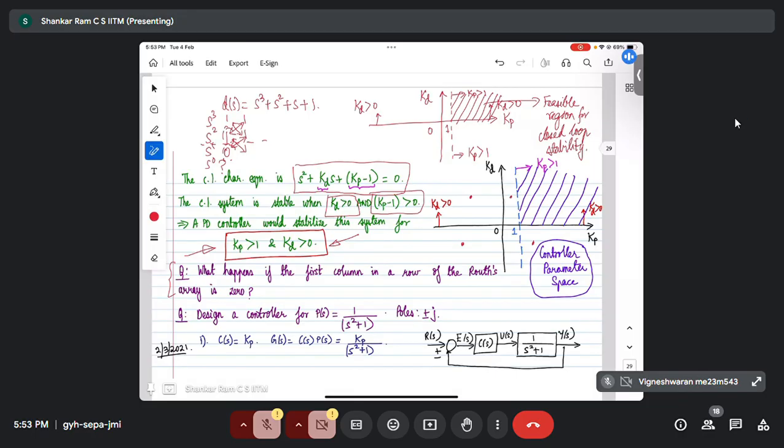So we may always get these special conditions. Those will be answered in that NPTEL video. Kindly watch it. I will also discuss what the physical implication is as far as closed loop poles are concerned. For you and me, for automatic control, we are very clear: we want all poles to be in the left of the complex plane. So you and I will design only those controllers which will ensure that all the coefficients in the first column of the Routh array are non-zero and on the same side. That's it. So this is what we would have learned in this particular video.